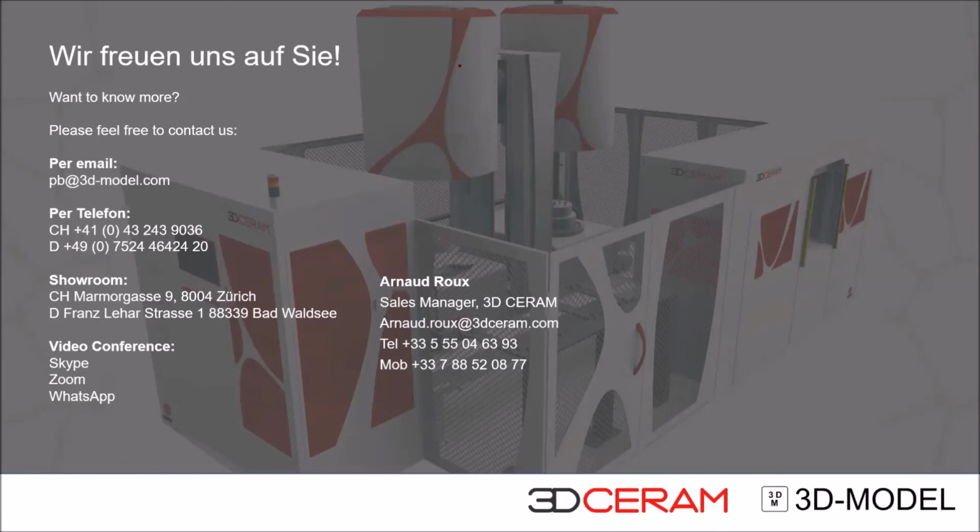Okay, you create the support and you just put the parts on the support, and you print the support and the part at the same time. Because we are polymerizing from the top and gravity is with us, the part will just lay down on the support with a small gap of unpolymerized slurry between the support and the part.